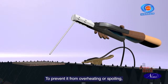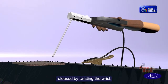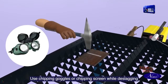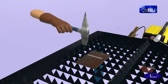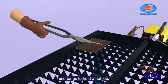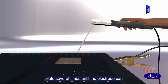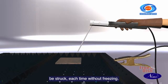To prevent it from overheating or spoiling, the electrode should be quickly released by twisting the wrist if it freezes to the plate. Use chipping goggles or chipping screen while deslagging or while removing slag on the welds. If the welded job is small in size, use tongs to hold a hot job. Strike the arc on the scrap MS plate several times until the electrode can be struck each time without freezing.